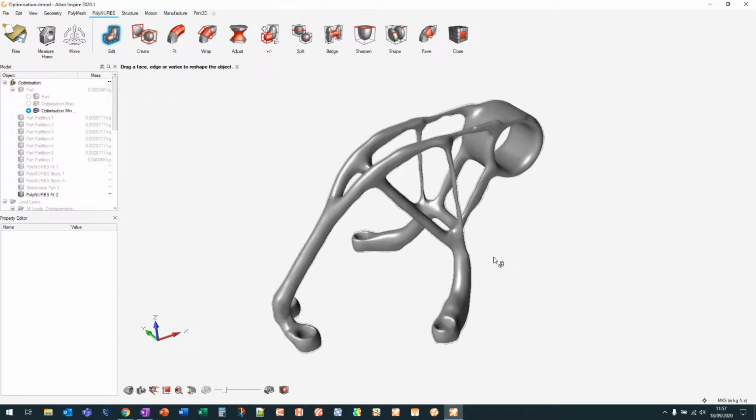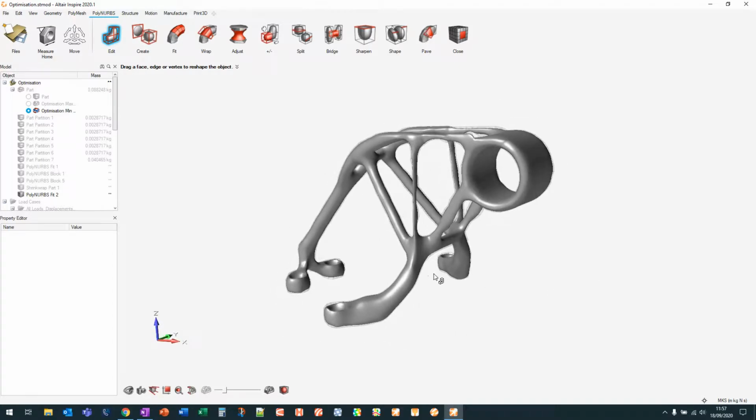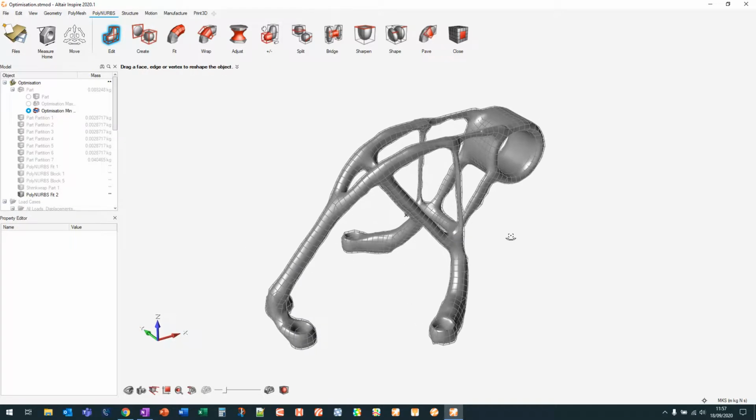So there are a couple of ways in which you can optimize a part and then take something back into CAD. They are quick ways, depending on the complexity of the part. You can use the wrapping tool, the automatic polynomials fit, or the shrink wrapping. It really depends on the use case. That's it for performing an analysis, and looking at the optimization and how that compares to your original design. I hope you can see that using the geometry editing tools, you can run through design iterations really quickly, or you can optimize the part based on that, and see how all these values compare using the compare tool itself.